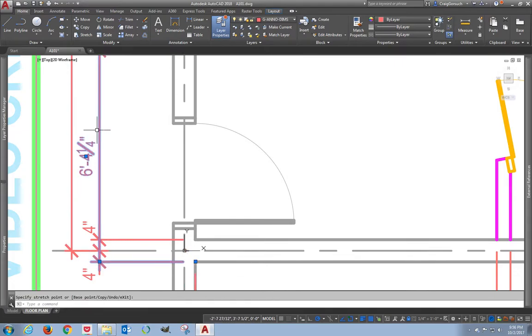You see how this dimension overlaps these other two? We do not ever, ever, ever want to do that because it's just bad math, and it's a bad condition all the way around, and it will lead to problems. I don't mind if these two lines overlap. We do not want this line to have other dimensions completely inside of it. That's just a problem.